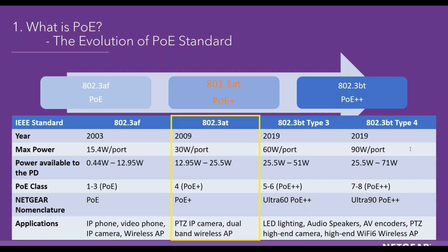Whereas passive PoE is non-standard-based PoE, which does not perform a handshake. It is extremely important to know what PoE voltage your device requires before plugging in the Ethernet cable and powering up with passive PoE. Otherwise, if you connect the wrong voltage with passive PoE, it may cause permanent electrical damage to the device, like the device will be burnt. Wow.